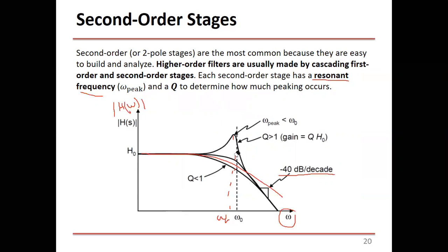Well, you might need this notch, okay? So, for example, you can make your design like this. Go flat, and then go high up, and then go down like this. Of course, this is not a low-pass filter for sure. This is a band-pass filter, a high-quality band-pass filter that passes the frequencies in this band, and rejects the frequency here and here. Because at this band of frequencies, the gain is very high, while below and above, the gain is very low. Of course, the gain is not symmetric below and above, but it's much lower than the gain at this frequency.